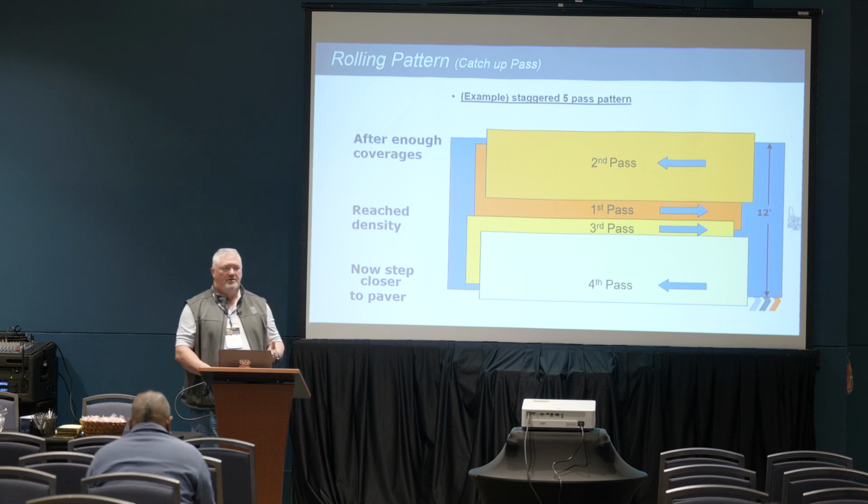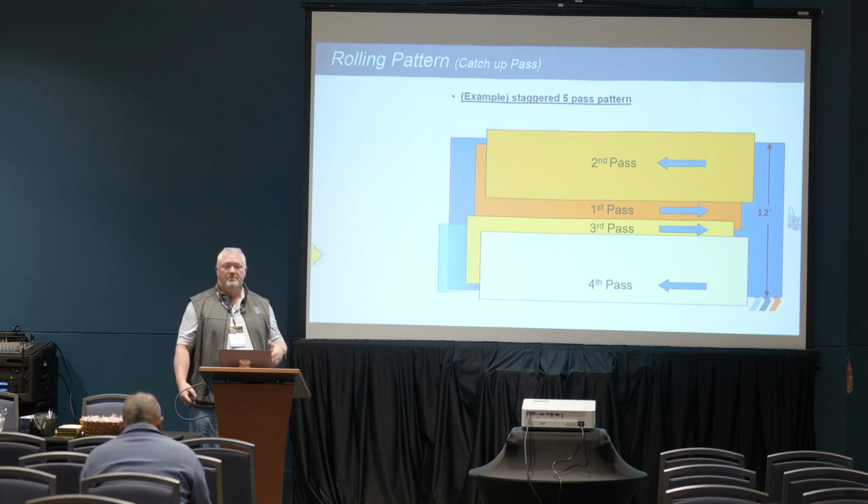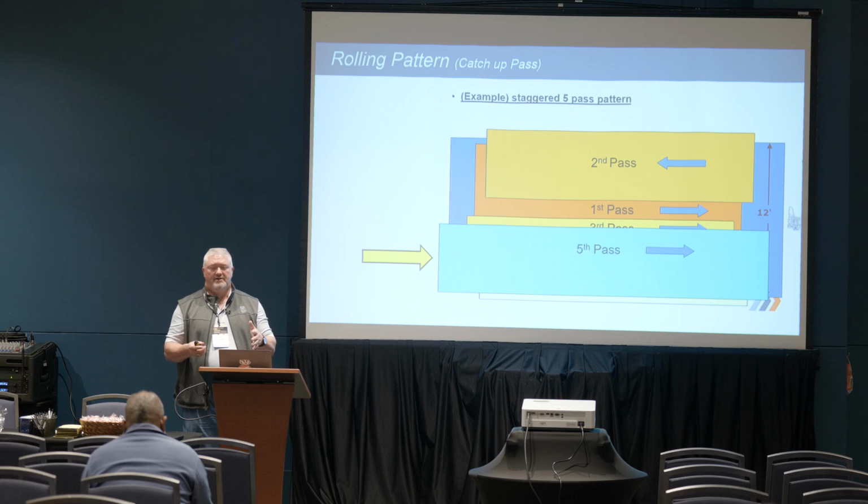Chance to tear it. I don't care if they go top or bottom. I always say go to the bottom because if you're going to push everything up to the joint, you're at least getting the outside edge compacted. And a lot of times the outside edge is the first one that has density that's a little bit lower than closer to the joint. So give the outside edge an extra pass.